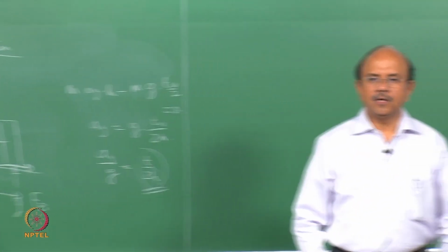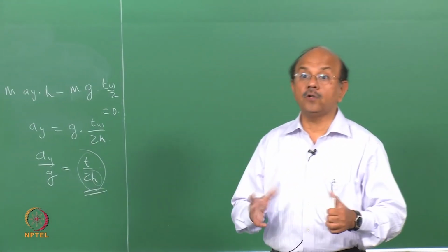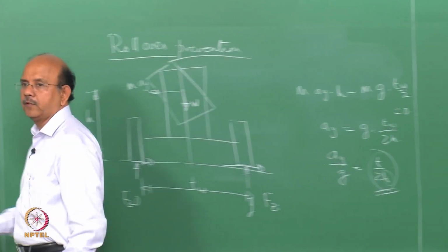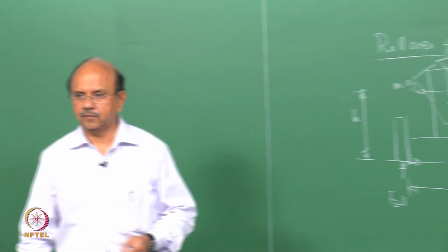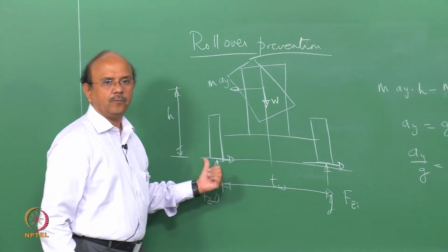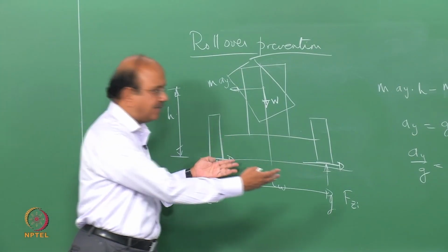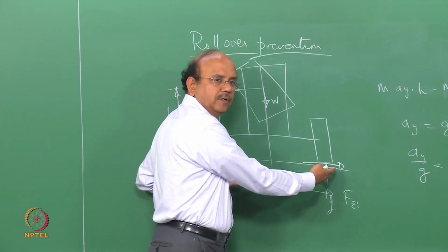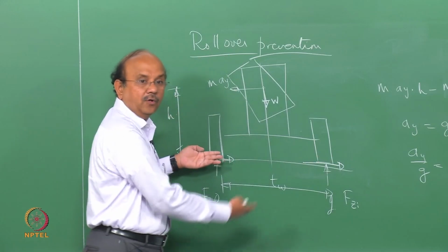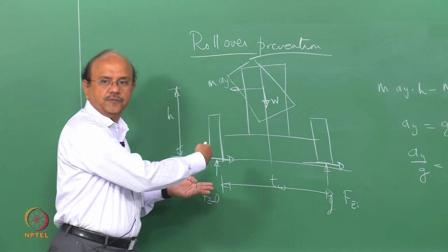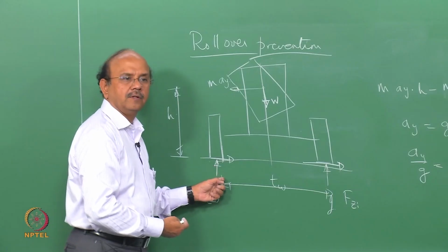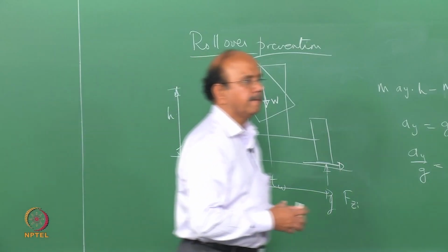The other factor, and the roll is also due to the stiffness of the tire. The tire stiffness is also going to have an effect. In other words, you can imagine that Fz on the inner tire is going to go to 0. The whole of Fz, that is the normal force, will be transferred to this tire.